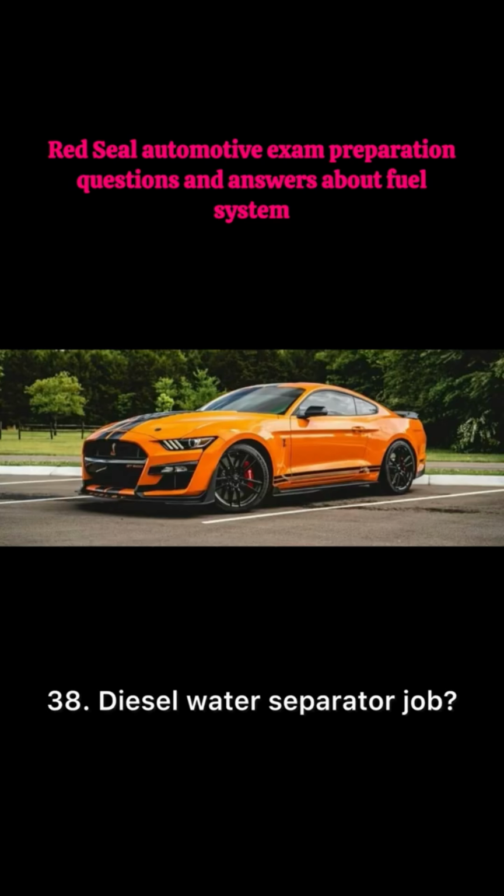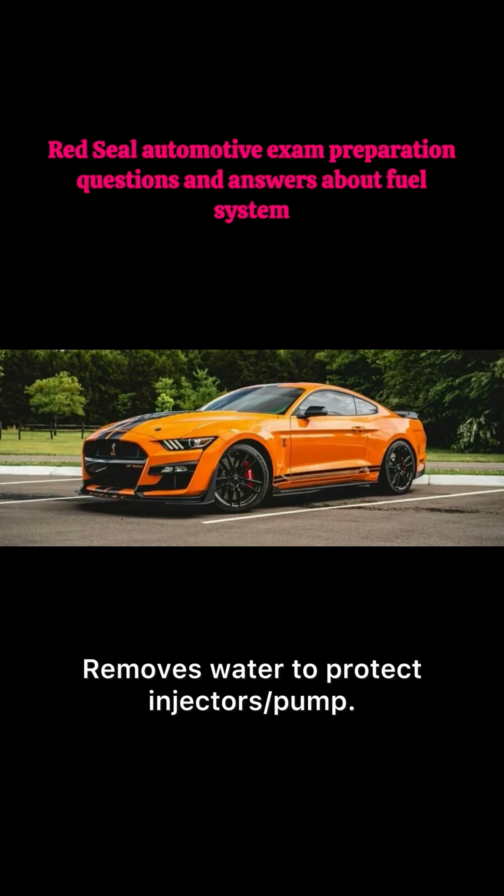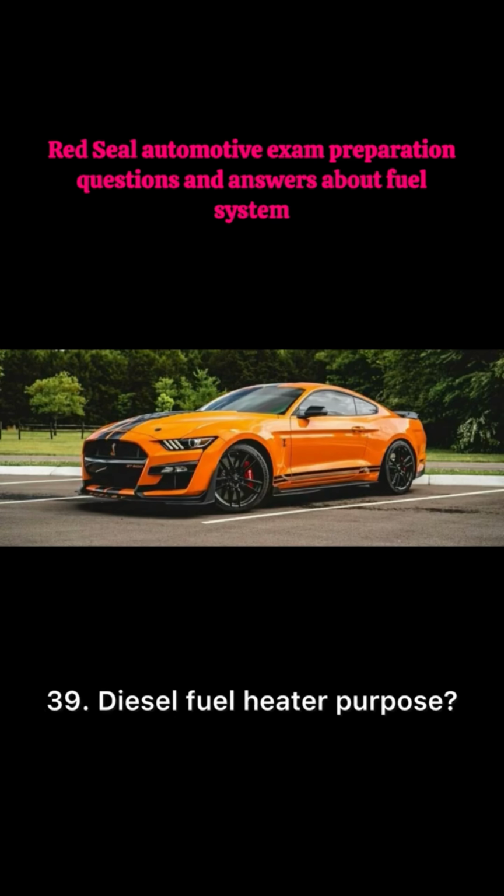38. Diesel water separator job. Removes water to protect injectors, pump. 39. Diesel fuel heater purpose. Stops fuel gelling in cold. 40. Common rail diesel pressure. 10,000 to 30,000 psi.